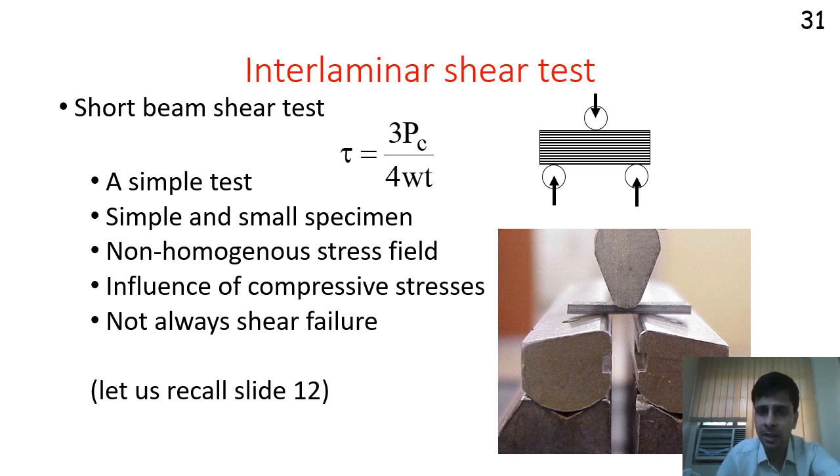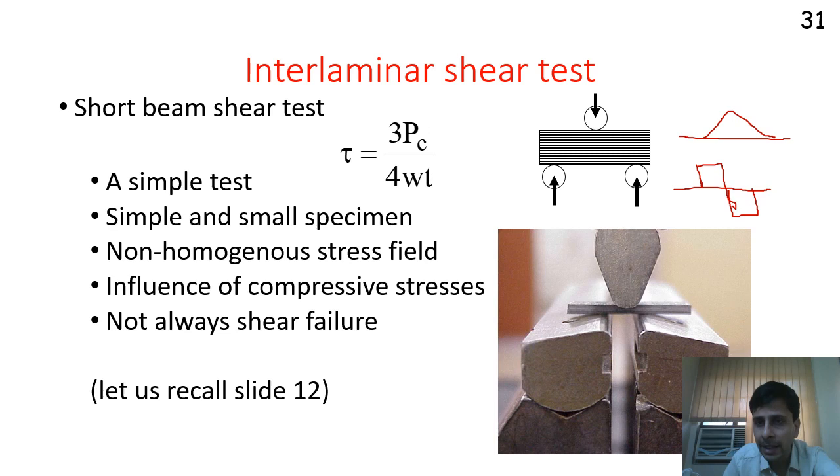But if my gauge length is very small, then you can calculate the bending moment, which comes out to be something like this. So the maximum bending load is a function of your gauge length, but the maximum shear strength is not a function of my length. So this maximum bending load can tend to 0 if my length is small, but my shear strength remains intact. So based on this, we can calculate the shear strength, not the shear modulus, but the shear strength, by using the 3-point bending test and keeping my sample size very small.